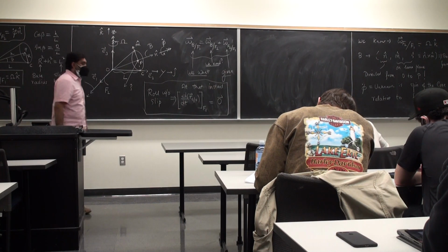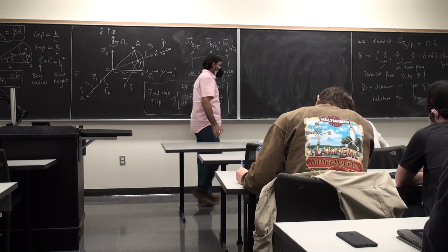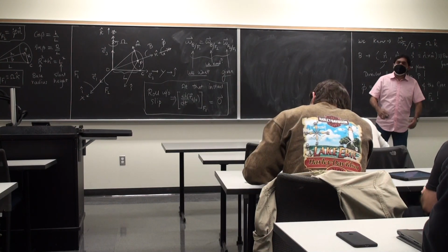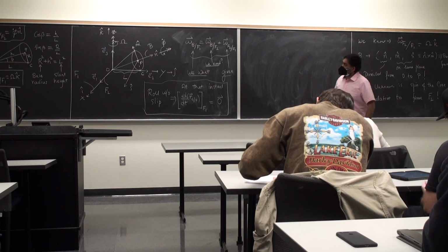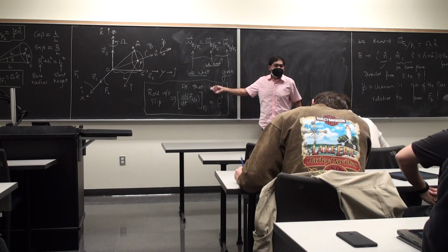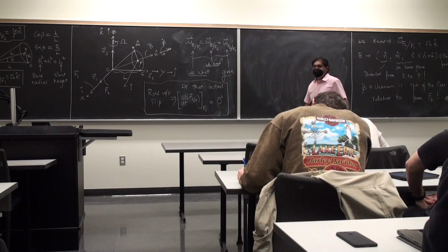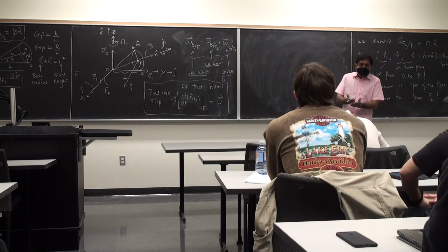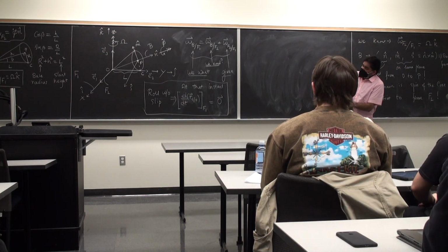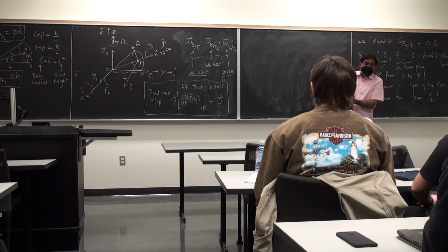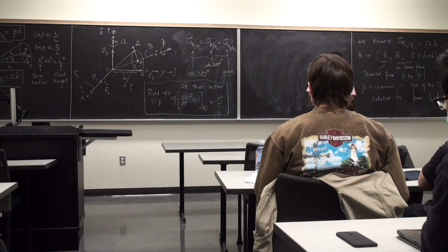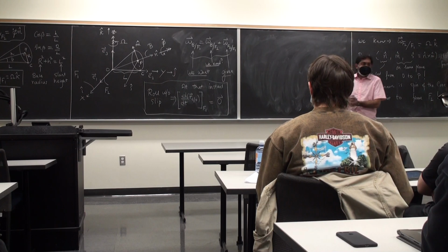And we will see what exactly defines a constraint, and what is not a constraint, using the idea of virtual work later down the semester. At this point in time, you just have to take my word for it. But it also makes common sense, right? If I'm rolling without slip, it means that my relative velocity at that contact point is 0. If my relative velocity is 0 with respect to a fixed surface, what's my velocity at that instant in time? It's also 0.